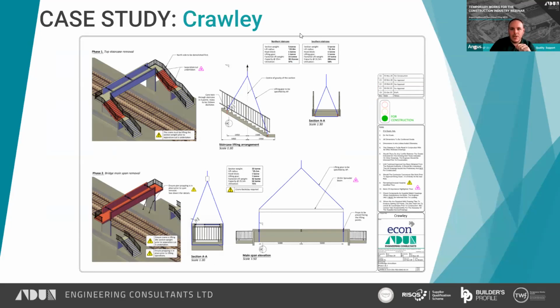A point that's worth mentioning is when you're lifting, you often end up with, especially if you sling around a structure, a horizontal component that the bridge probably hasn't seen before in its life. Simple solution to that is a push-pull or just an acro prop across, as long as it can take the theoretical horizontal load. Otherwise, you've got to try and somehow justify that the parapet will work, even though it probably will. It's simpler sometimes to put a simple acro prop in place.